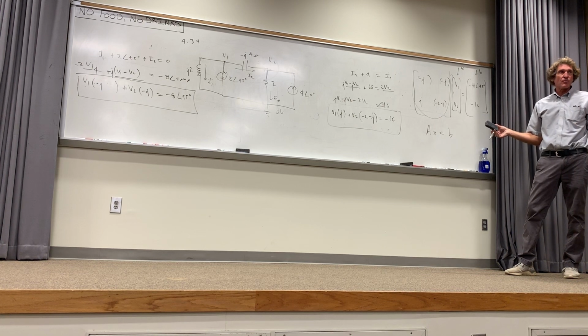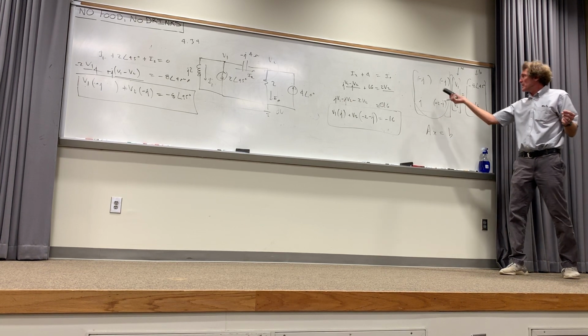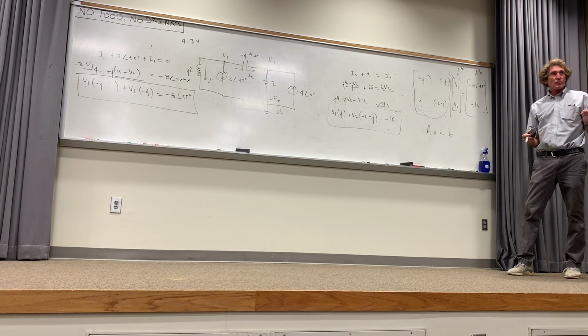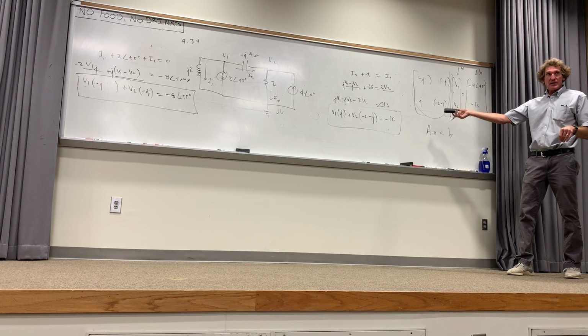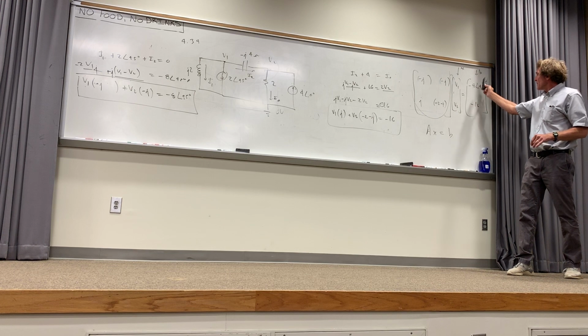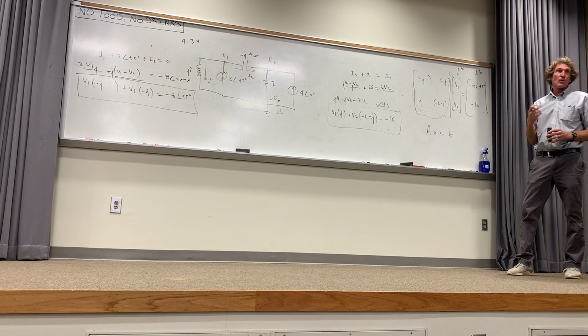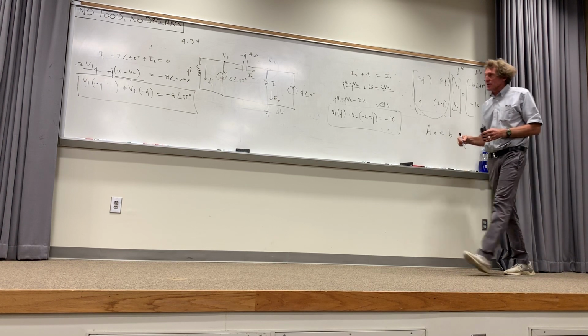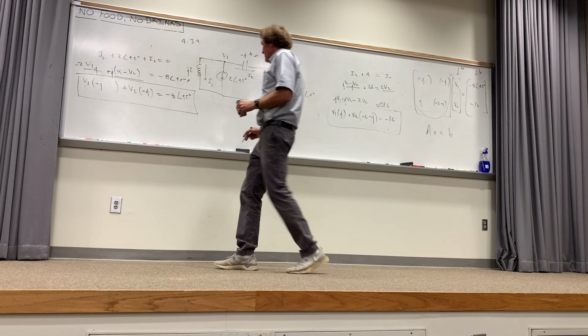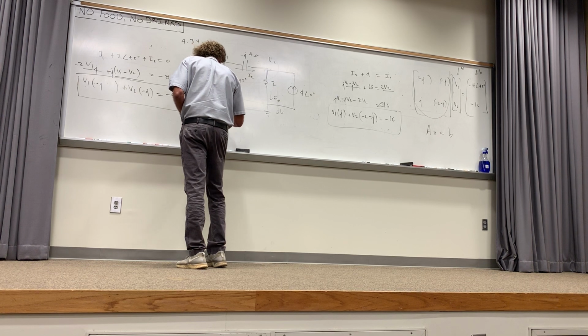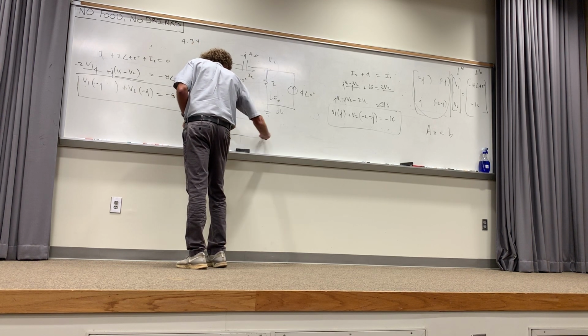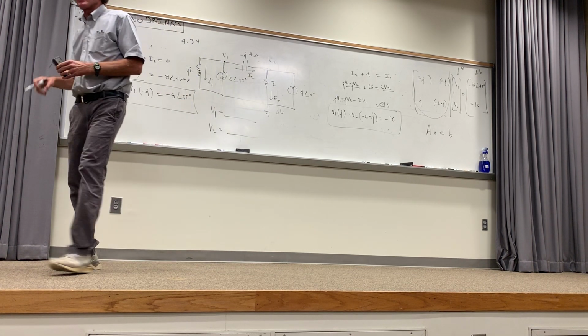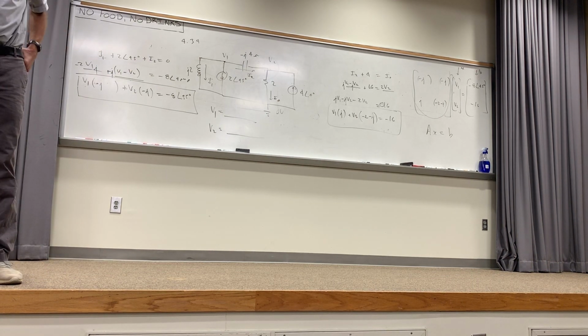When you have solvers in your calculators, they'll have something that allows this form to be entered. I don't know what forms you've got, but basically you're going to be entering these as A11, A12, A21, and A22. And then this is simply B1, and B2 is going to be a column vector. Y'all see this, class? And then you gotta solve it. So then you gotta give me V1 and V2 in polar form. I wanna see what you guys get. V1 and V2. Now this is polar, so it's magnitude and angle. You're gonna have to do this and do it efficiently.